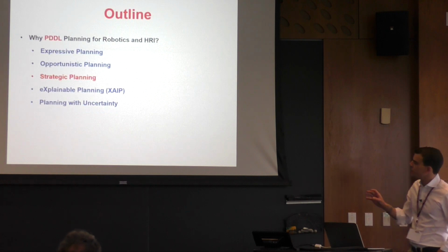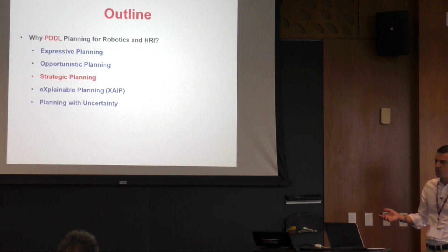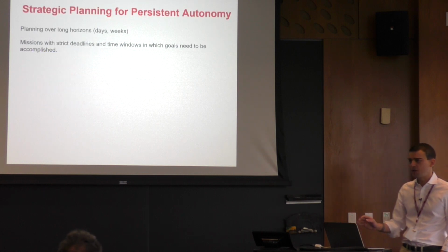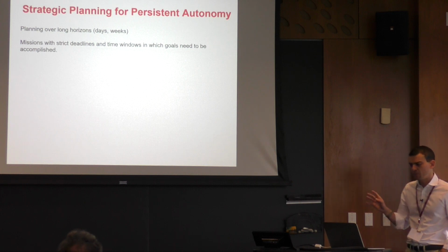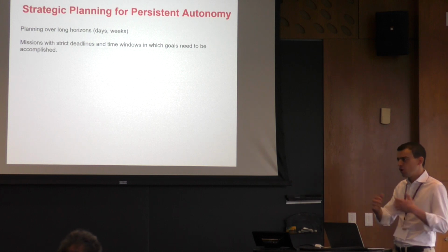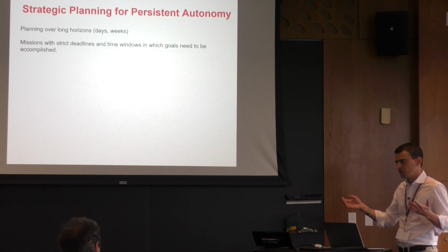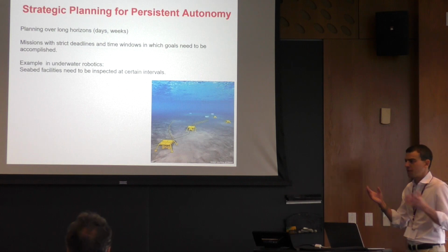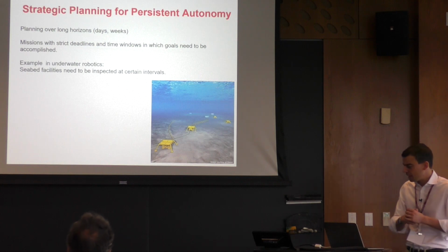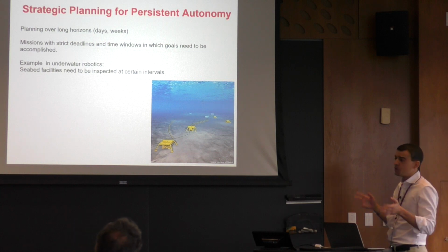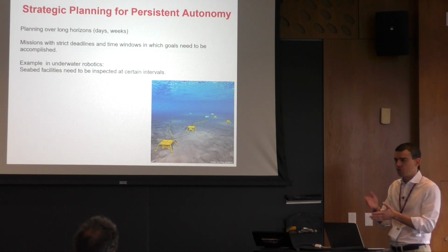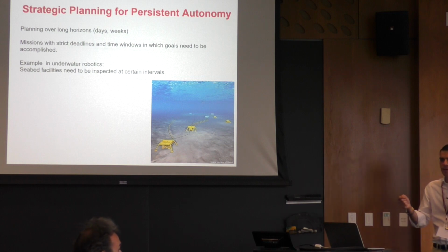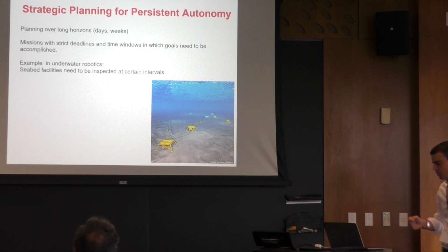Quickly on something, another reason why PDDL planning is useful, which is strategic planning. Here, still in the domain of underwater robotics, but this is generalized to many other domains where you have long missions. You need to plan for long horizons, and as we all know, planning with long horizons is difficult because the state explosion is huge. Moreover, you have time windows, meaning that there are tasks that you have to do only in specific time windows, and you need to plan making sure that those tasks will be done in those time windows.